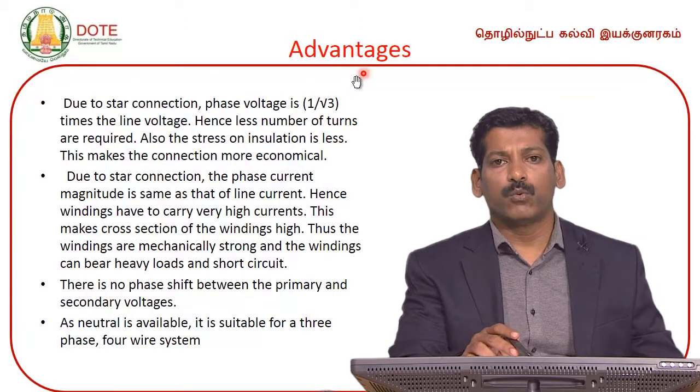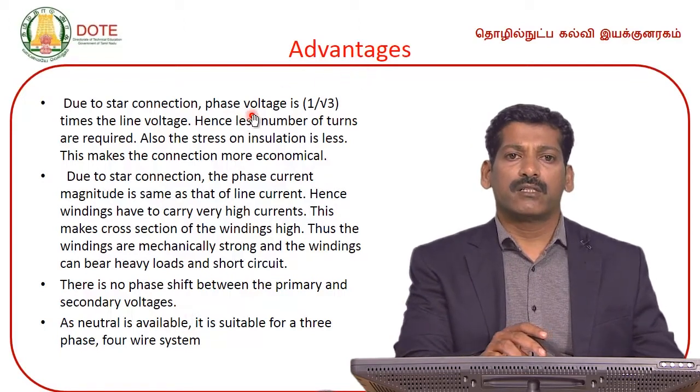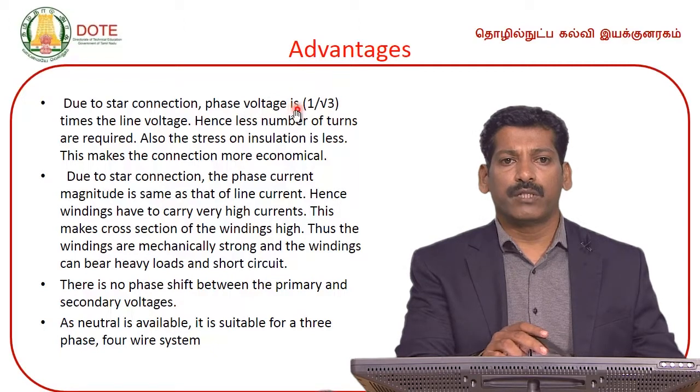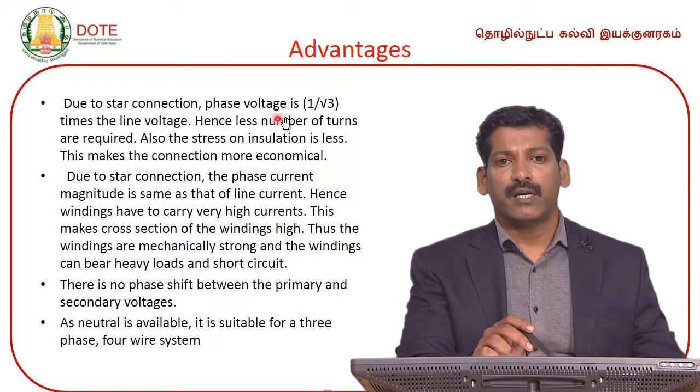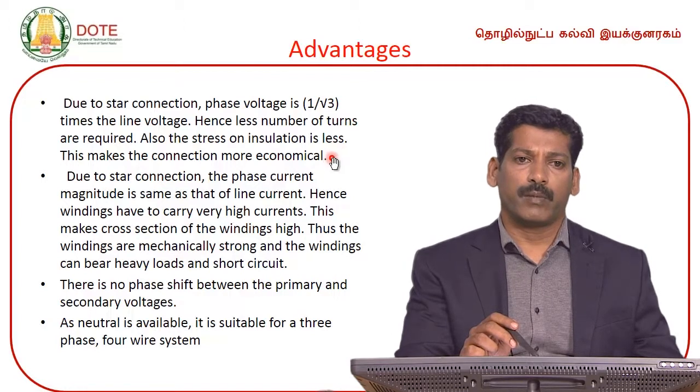So, here are the few advantages of a star star connection. Due to star connection, the phase voltage is 1 by root 3 times the line voltage, hence fewer turns are required. Also, the stress on the insulation is very less. This makes the connection more economical.